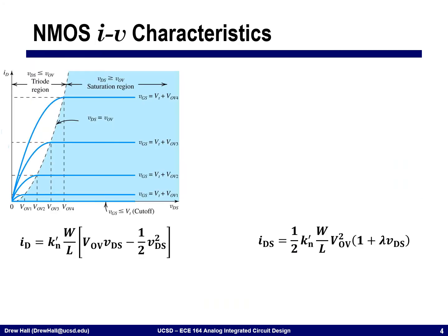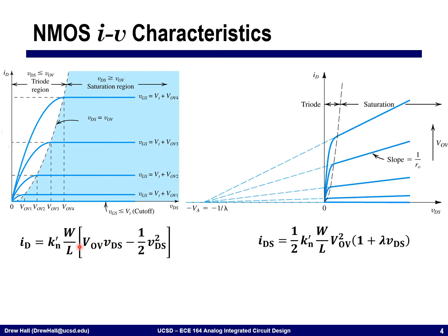All right, then we spent a lot of time talking about the actual characteristics of the transistors, understanding the different regions of operation, when the device is in triode, when it's in saturation, when it's in cutoff. We even talked about some of the advanced techniques, such as when the device is in sub-threshold. And we know that in that case the current doesn't actually go directly to zero, but that we do have conduction below VT. We derived both of these equations in terms of their fundamental device physics, so we understand where all of the terms come from and how they're all set up.